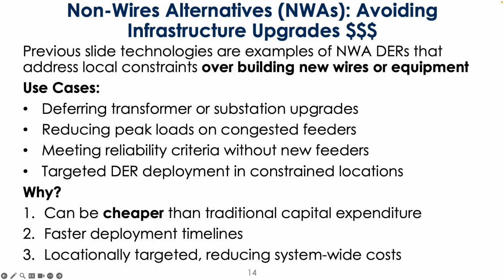But you can imagine just on a really hot day where your load approaches your capacity reserves, there is a utility program that controls smart thermostats, and they'll just turn off a bunch of AC units, right? And that doesn't require telemetry at the distribution level. We just need to know the relative load versus capacity in the aggregate.